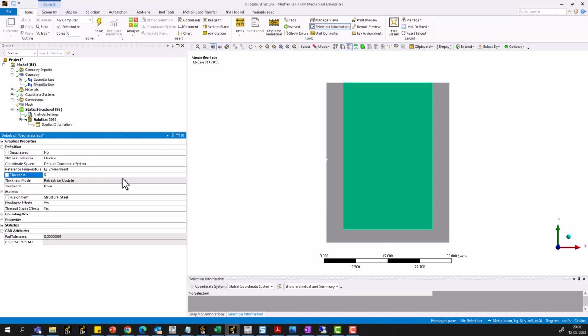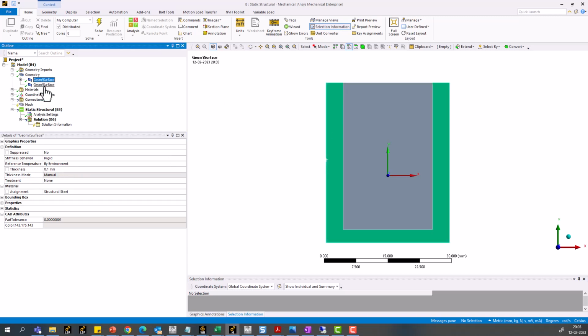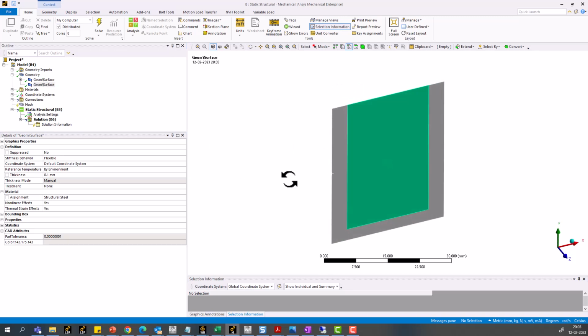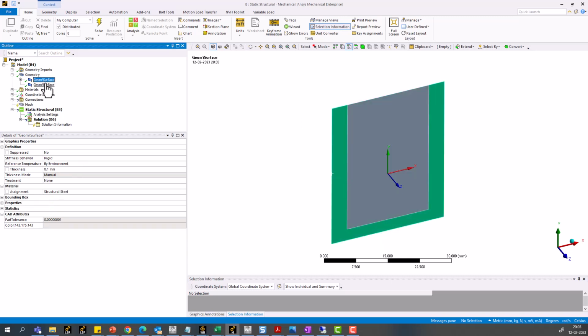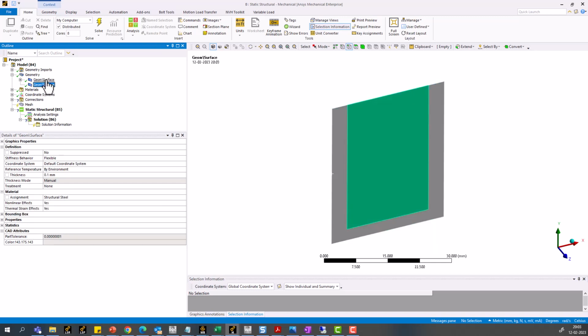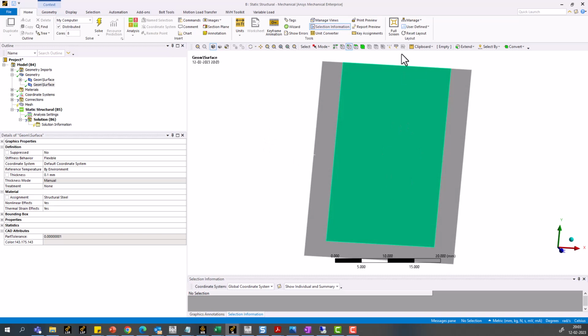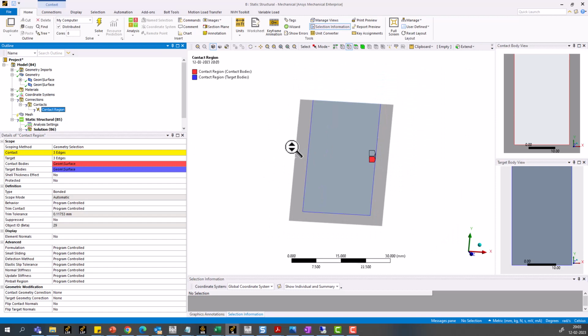The only thing is that I have to change the thickness to the same value that I'm using here. So we cannot use different thickness values for the different cases. The only thing is that some loads will get transferred differently. I will discuss those things in one of our upcoming videos, like how this thickness affects the plane stress behavior. But for this problem, let's focus on our main objective, that is stress and the deformation at this specific location.